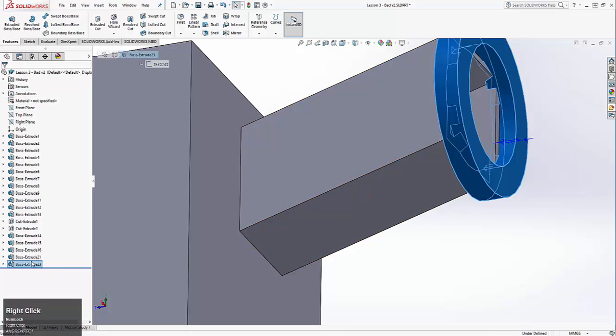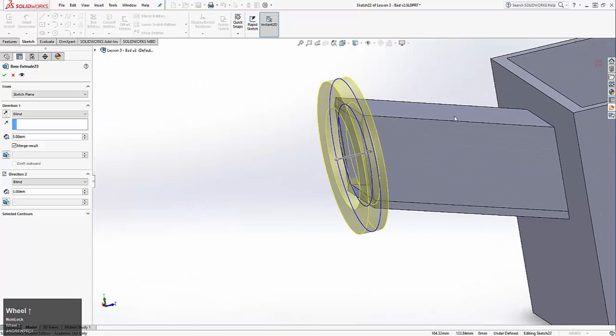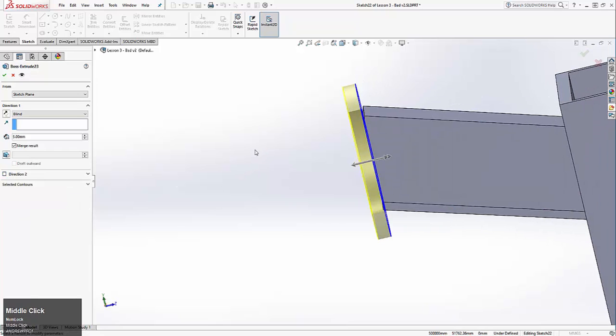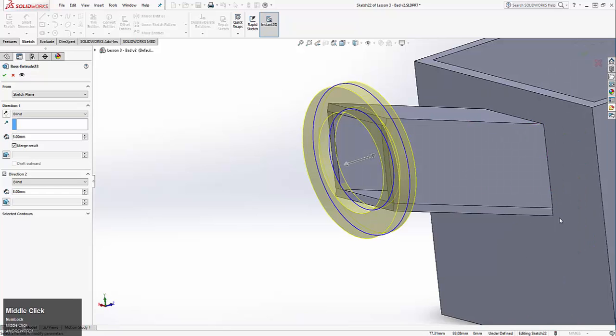And finally, we have this weird ring, which isn't doing anything except to like try and be a circle on the end. It even has a second direction out the back, which it needs. I'm going to disable it for a second to show why. It's because SolidWorks is going to say, oh no, there's a 0 thickness issue, which means that it's trying to extrude out in a place, and it would create an area. I don't know why I can't describe 0 thickness very well. Just an area where there is no thickness, like an edge, trying to extrude an edge or something like that. Yeah.